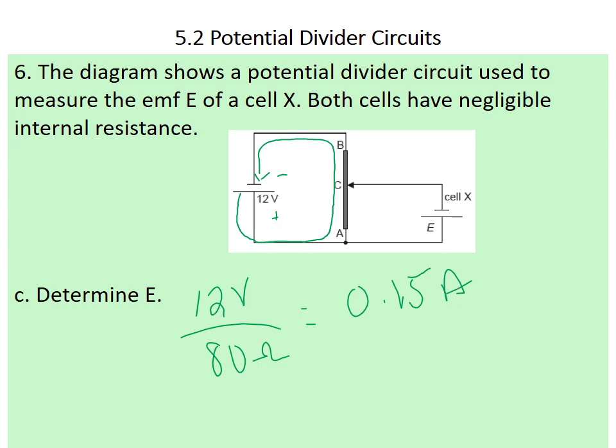This potential divider circuit, the position A to C has been chosen because if we were to reposition maybe a little bit lower, maybe right here, current would flow through the circuit, and this position C is the limit where no current is flowing through the circuit. That means that right at this point C, we have managed to match the potential difference C to A, this delta V, with the EMF supplied by the cell.